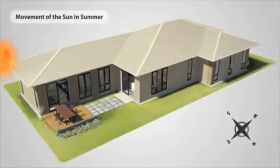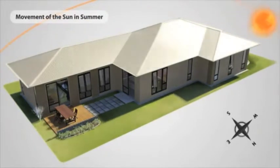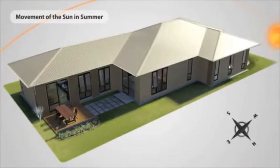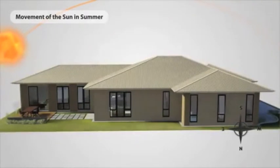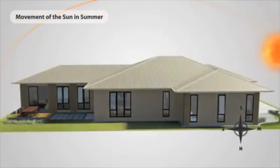The movement of the sun in different seasons is important to understand when designing a house. Here is the movement of the summer sun. It is high in the sky. You can maximize shade in the summer by designing eaves or overhangs on your house. Here you can see the sun does not stream into the north side window, which creates more shade.